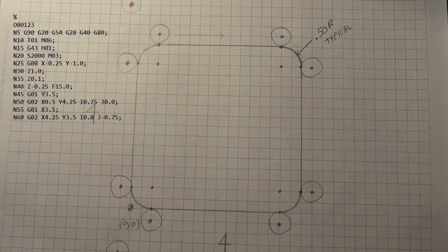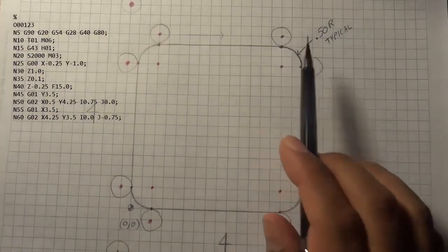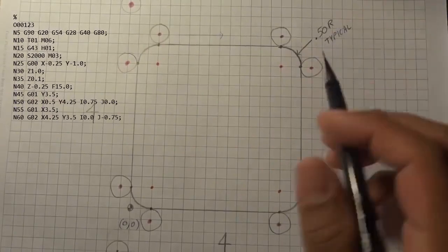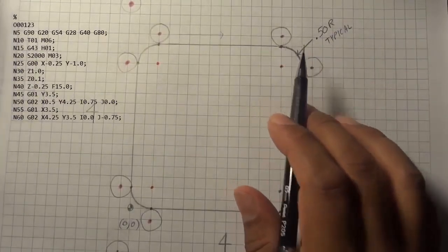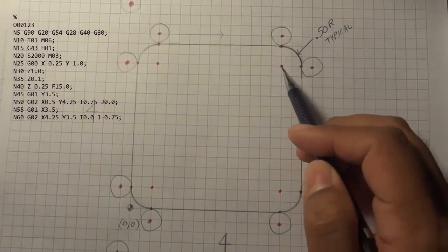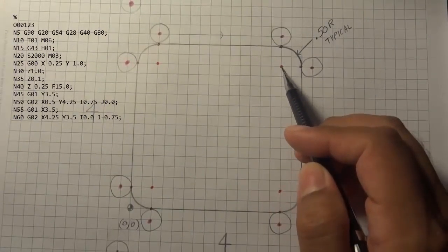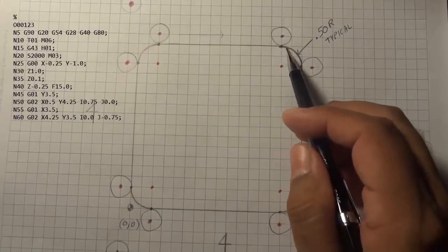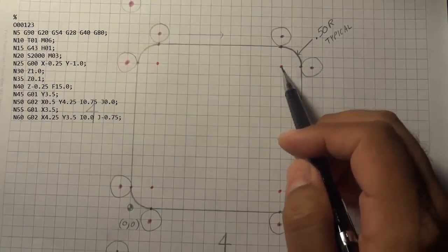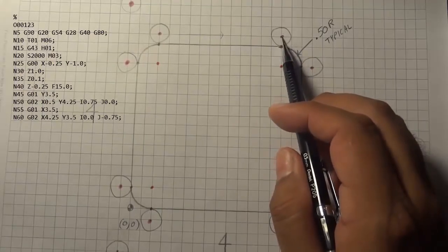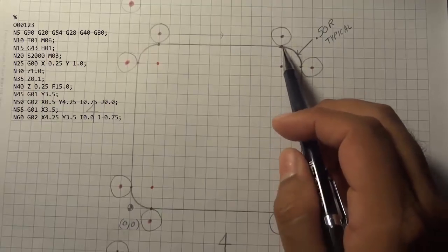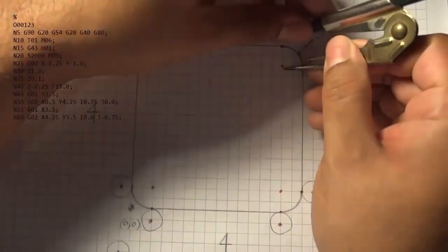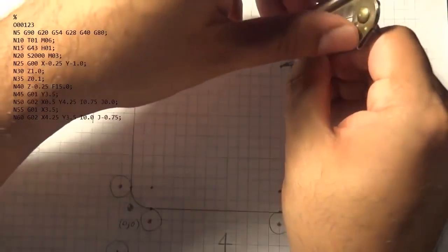But when we make our cut using this cutter, the cutter is going to create a different radius, and actually this radius is going to be 0.75, because our arc center is right here, and from arc center to the radius is 0.5. That gives us our 0.5 on the part. But from arc center to the starting point on the center of the cutter is a 1/4 inch, 1/2 inch, 3/4 inch. So in this case the radius will be 0.75.